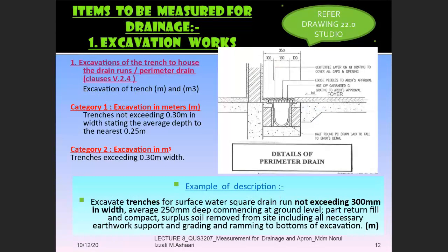So basically, if we go through one by one, item number 1 under section V.2, you can refer to your studio drawing number 2. We have to measure excavation to the trench, but according to the width of the foundation. So can everyone refer to section V.2.4? There are two categories of excavation according to the width. First category, you have to measure in meter. Second category, you have to measure in meter cube.